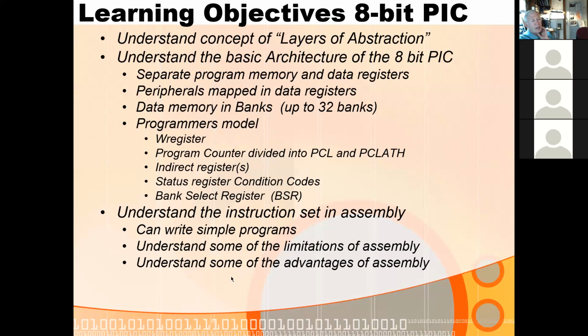On our chip, we have kind of their legacy touch sensing module, which works great unless you happen to have interference at just the wrong frequency, and then there's nothing you can do to fix it. For our purposes, it works fine. It works actually very well. But in order to get around that, they finally had to use special ADC modules that are called ADCC modules. They're computing converters as well.